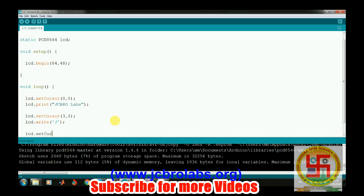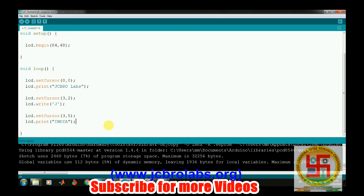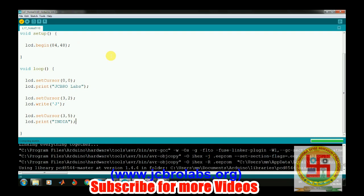Now let's write another word as well. So let's change the cursor and make it third location, comma, last line of the LCD, and then we'll write lcd.print. We can print like India. Okay, so that's it. That is a simple program. Let's save it and let's generate a compile binary, or I should say the hex file.